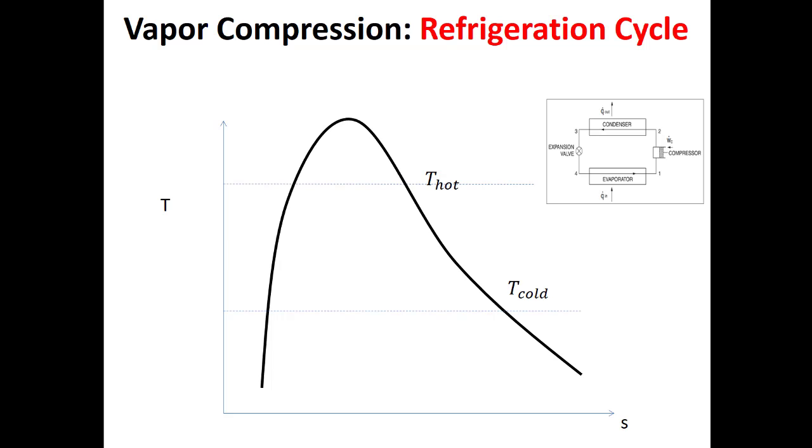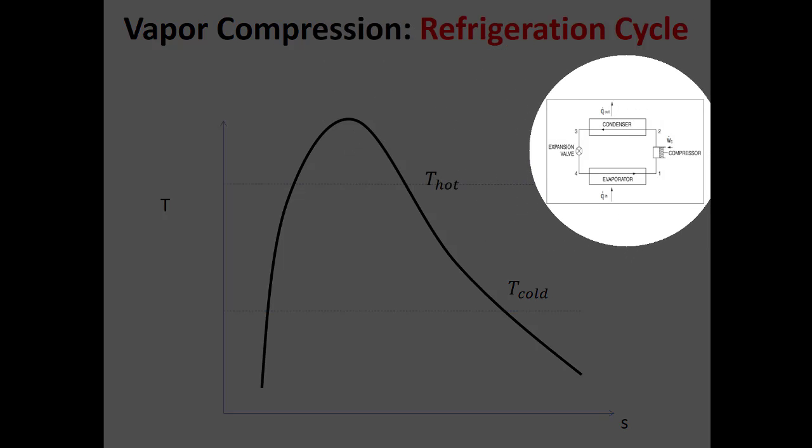So it's nice for us to be friends with chemical engineers because they're always making new chemicals. So things like new refrigerants that still have good performance, but are more environmentally friendly. But what's happening thermodynamically as we run through this cycle is we're moving back and forth across the vapor dome, just like we did in a Rankine cycle, right? And you know this maybe because of the names of our heat exchangers.